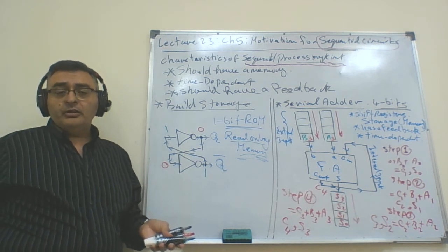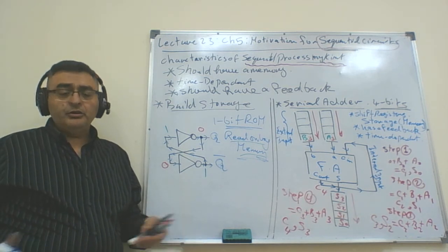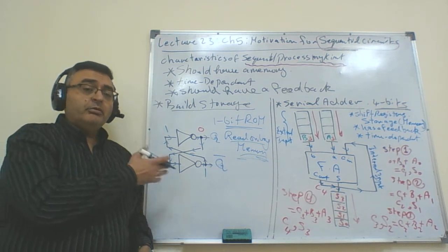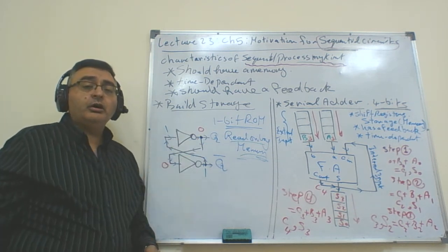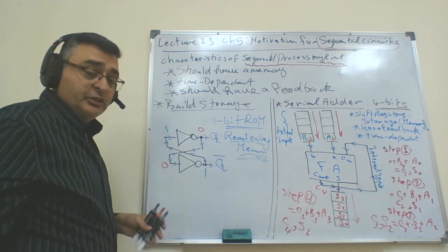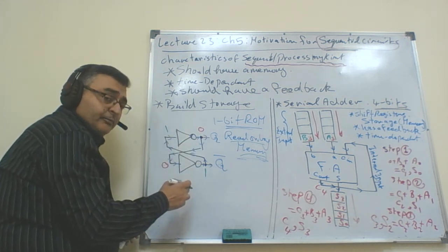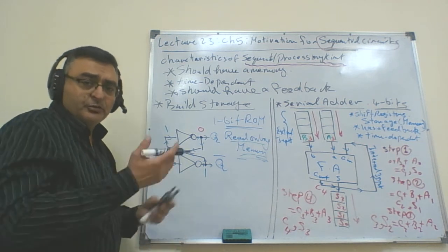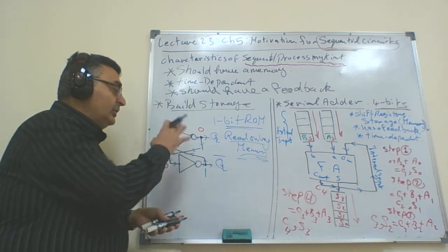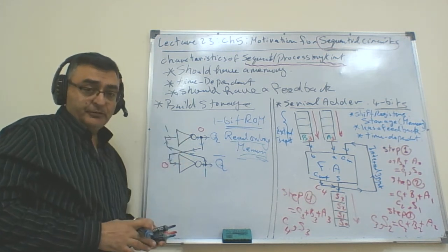It's storing the logic forever with no possibility for changing it. However, without applying anything, you are producing an output. Is this a sequential circuit? Yes, it's connected to the feedback. There is no time dependence here because the circuit is not changing, but I have at least a value stored here forever.